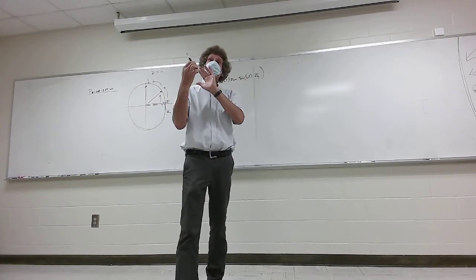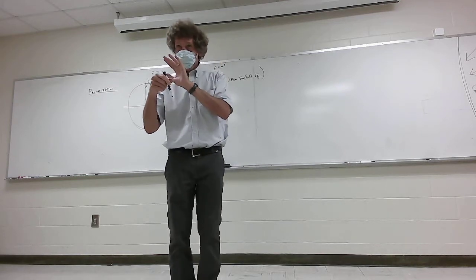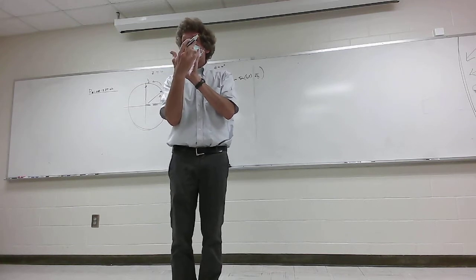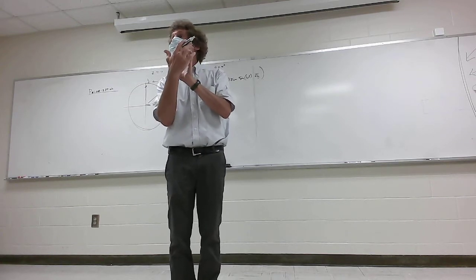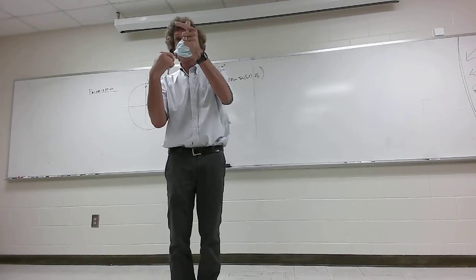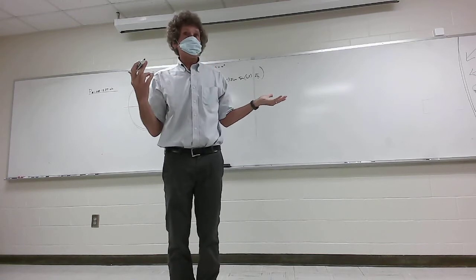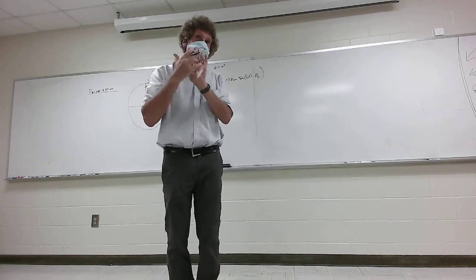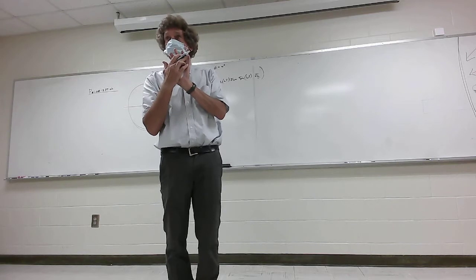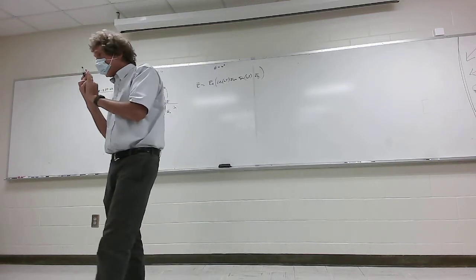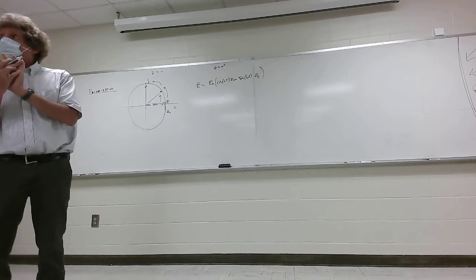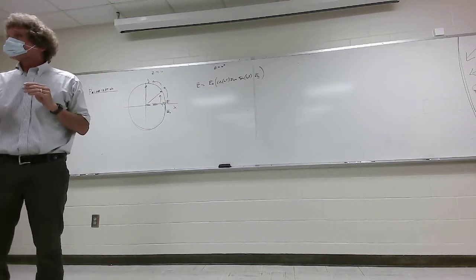Now, anything that reflects back that's a left-hand wave goes through a filter, and my filter's frequency dependent too. Hear me on this, and they're easy. I mean, they're not easy, but you can build them. Then anything coming back that's got the right frequency, right polarization, now I process that information and see what the time delay was. All right? Now I can figure out distance to target, and by doing that several times, I can find velocity. You're going to find more about this in a bit. Y'all follow me? So that's why right-hand circular polarization is so important.